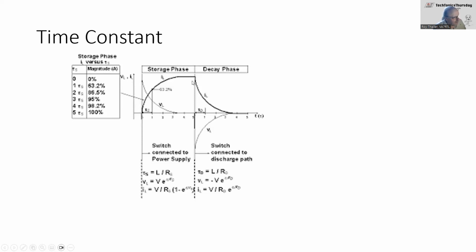But it's pretty well the same curve, but different values. So for the advanced course, you'll need to know this, and they'll ask you how much the capacitor charges in 3 time constants and things like that. So it's the same for the inductor. The time constant here is the inductance divided by the resistance, so L divided by R. And we'll look at capacitors next week.